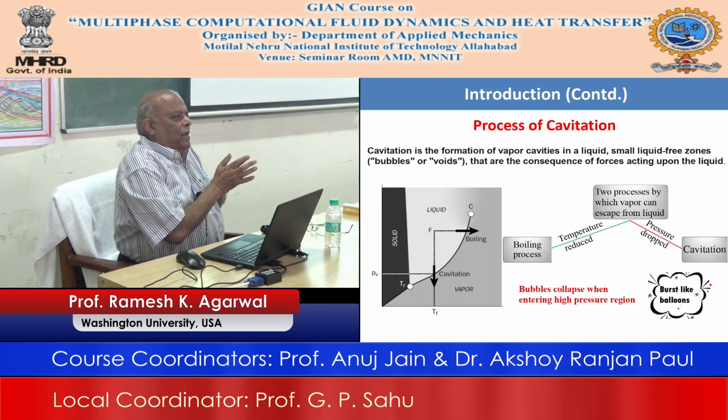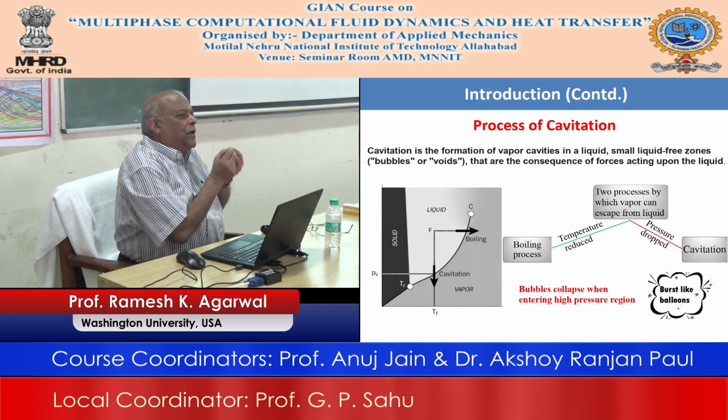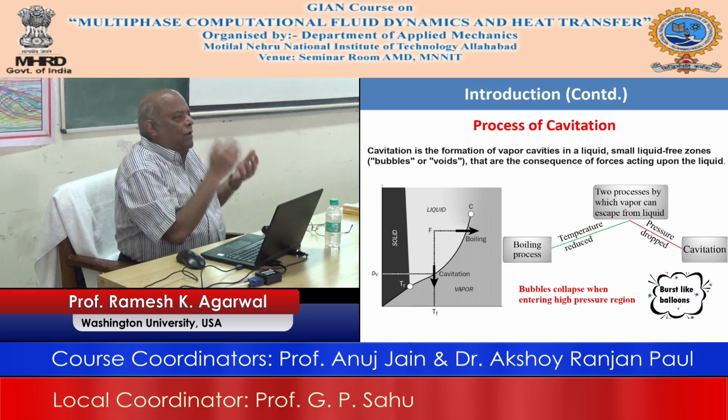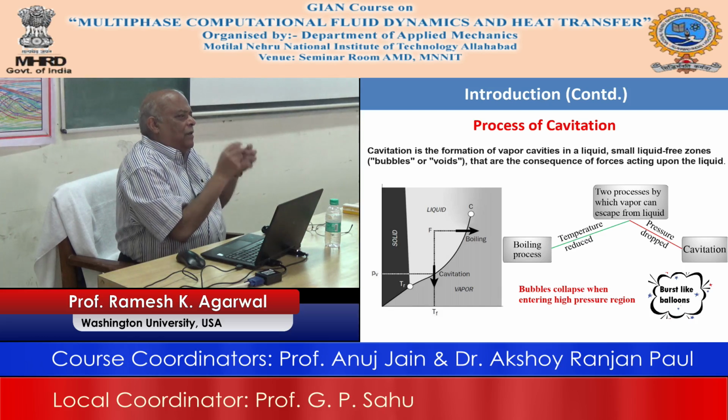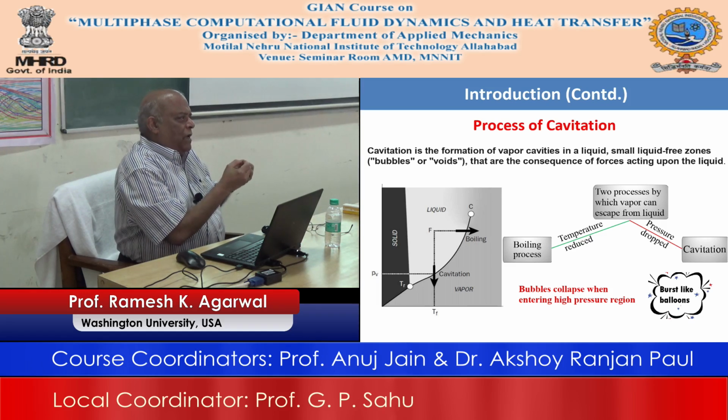Okay, so if you take Fluent, first of all, under certain flow conditions, it should be able to calculate where the low pressure is. That is the number one requirement, which it can do, because from the momentum and conservation equations it can easily calculate where the low pressure is. As soon as you calculate low pressure, it identifies the areas where the air is going to be. So you have to assume that wherever the low pressure occurs, which Fluent calculates, all those mesh cells in which the pressure is low are going to be a source of air or source of cavitation.